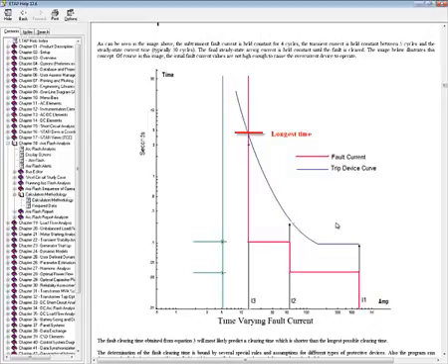If we were doing the analysis based on a static methodology, you would either find the response of the overcurrent device based on I2 or I1. But when analyzing based on the decay method, it will consider these three currents to find the actual time, which will have to consider the steady state current of the generator. So let's go ahead and show an example of this behavior in ETAP software using the arc flash sequence of operation tool.